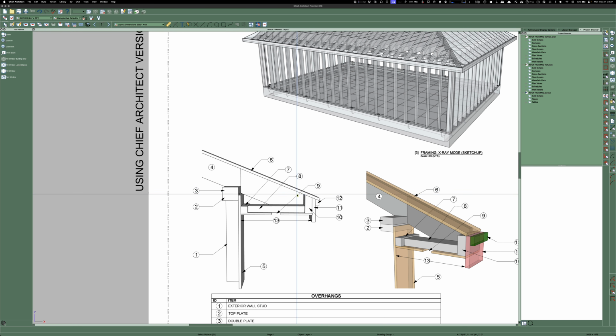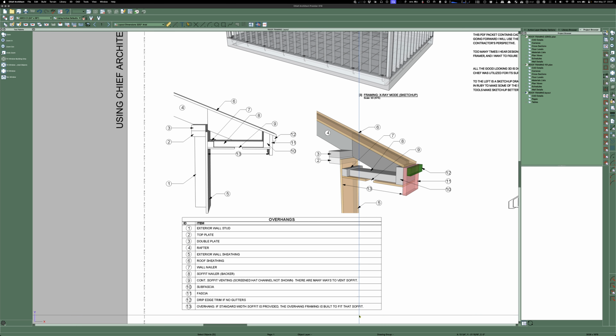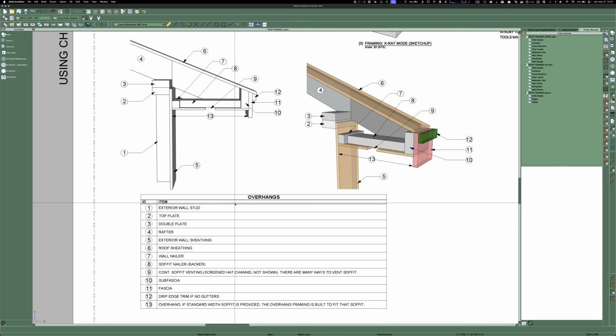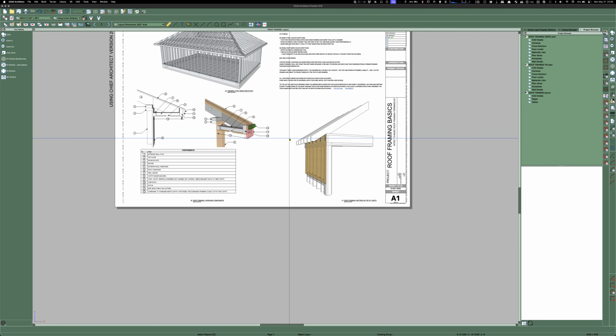So I've come up with this PDF that you see here before you, and I'm going to include a link once it's complete, in the video. You don't have to do it my way, but we can start using terminology that maybe sounds similar. Or I would love to hear in the comments how people share how they do things. This just happens to be a closed soffit with middle continuous venting, but you could cut in those 8x16 screened vents. You could use a solid piece that's all perforated. There's so many different ways to do this.